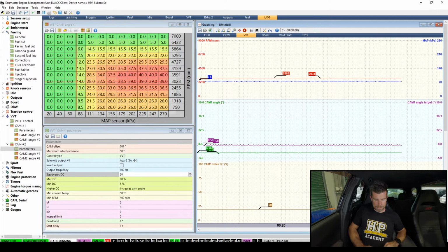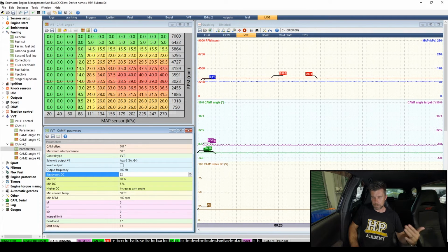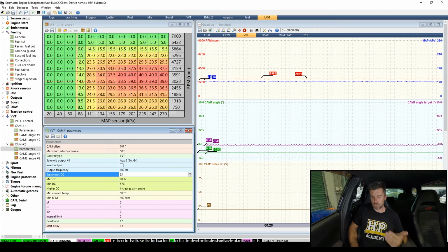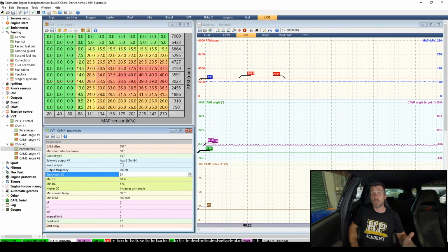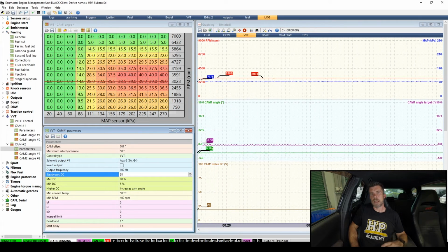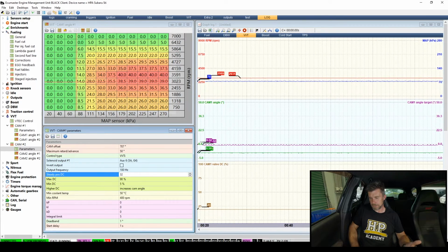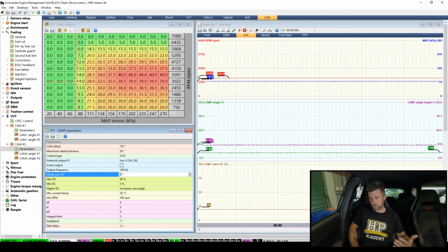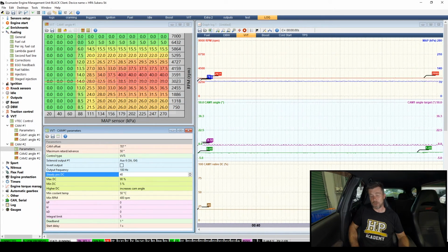So what we're going to do now is start by setting up our steady state position duty cycle, and to do this we're starting at the minimum value I can enter there of 20%, and we're just going to use the up arrow key and we're going to increment that, and we're going to be watching that green line to see when that starts moving. Generally we're going to be close to 50% duty cycle when we can expect the cam position to move, but there's still a range there, probably within normally plus or minus about 5% duty cycle. So let's just step ourselves up here, coming up through 35, 38, 39, 40% duty cycle, so we can see that incrementing on that brown line at the bottom.